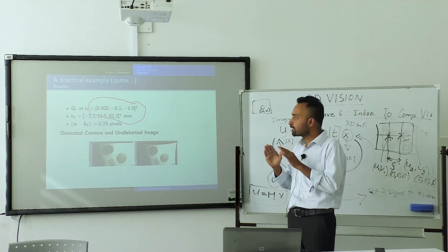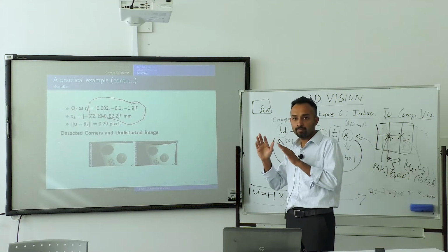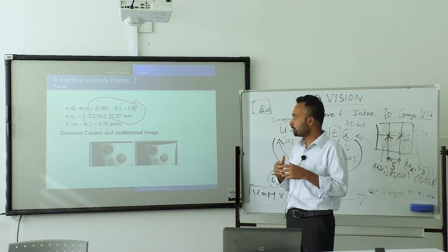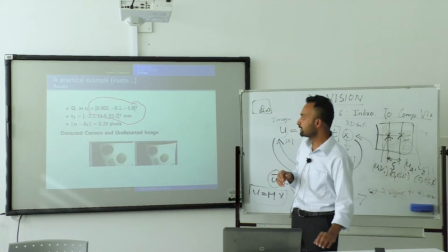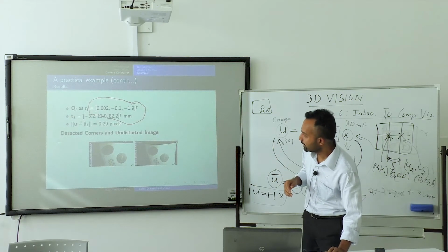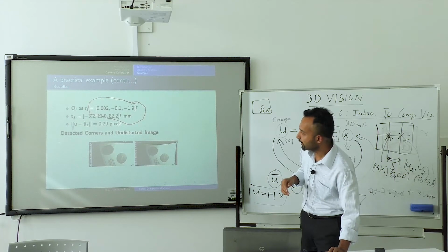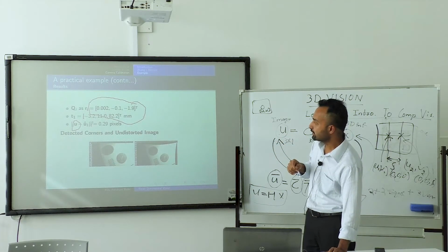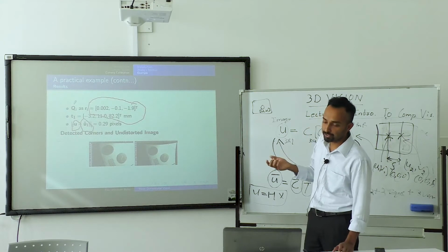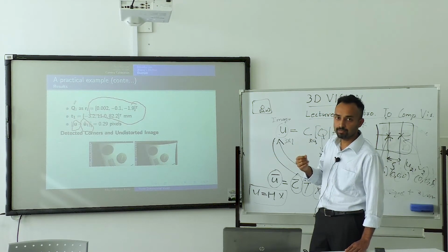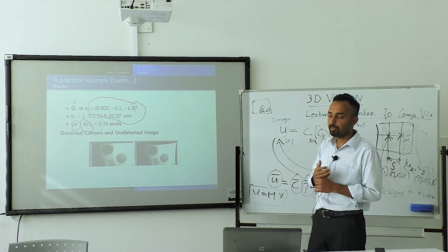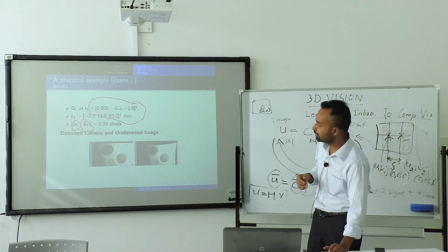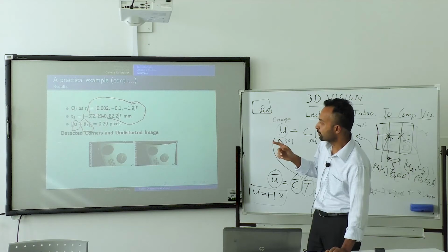So the final result, whether your camera calibration has been successful or not, or whether it is satisfactory or not, is measured by reprojection error. This is measured using image processing techniques on the image, and compared with what you have calculated using whatever you have estimated, that is the camera intrinsic matrix and the distortion parameters, etc. And this value is approximately 0.29 pixel for the first image.